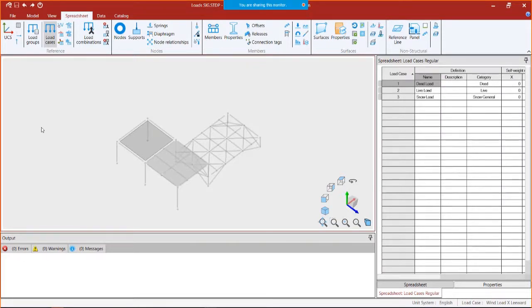Now when I talk about load cases within the Physical Modeler, what we're basically talking about is the cases that are going to be used to create your primary load case details. So if we remember what the load and definition dialog looks like in the STAAD.Pro Analytical Modeler, these would be the primary load cases that are in the load case details list. As you can see for this particular model, I've already created 3 load cases.